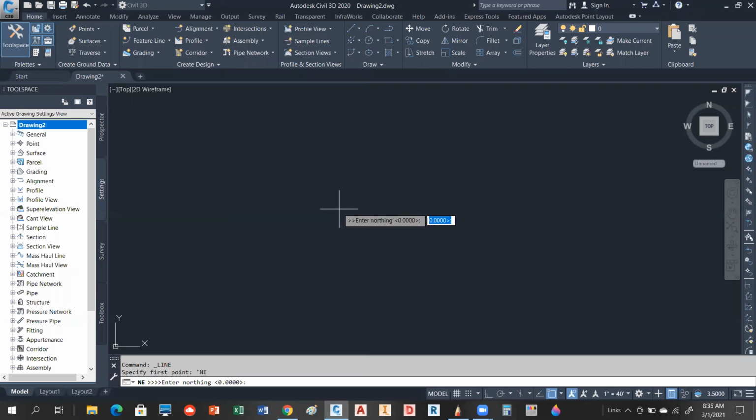So the first thing it's asking me is my northing value. I'm going to type in what I have, 2640.5836. Now, the reason I've given you such high values is because you do very often work in 4 decimal places. So once you have that, you just hit enter.